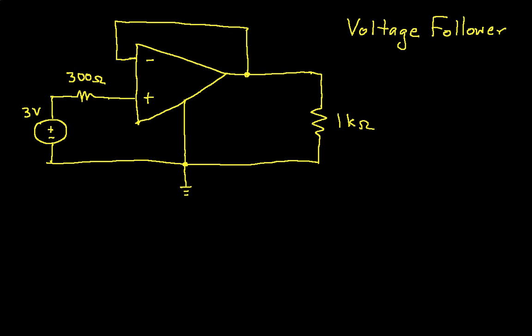First, we'll use the realistic model, it's sometimes also called the non-ideal model, where we have an input resistance. And in order to show you how this stuff works, I'm going to make the input resistance fairly small relative to what it would actually be. I'm going to have it just be 1 k ohm.